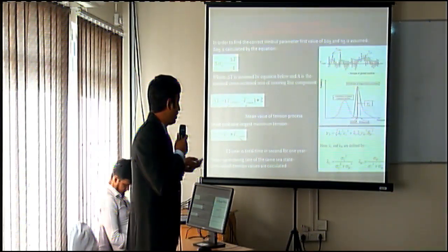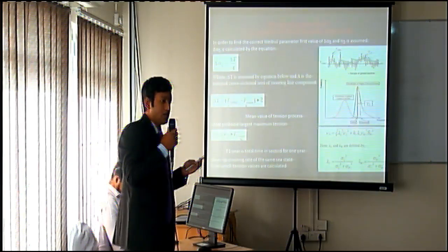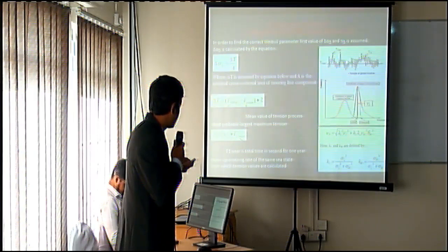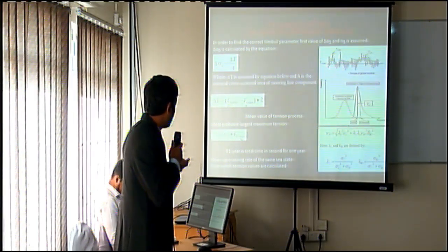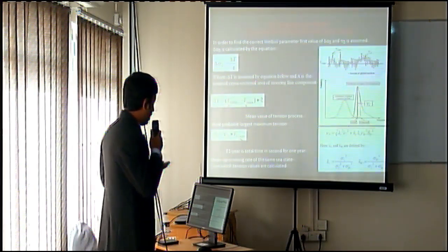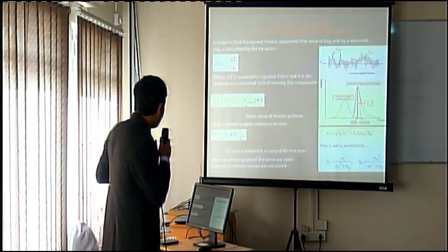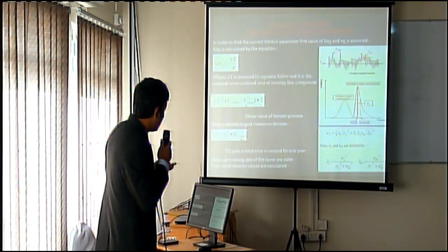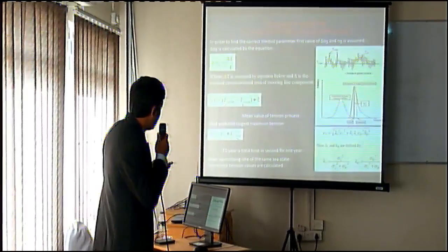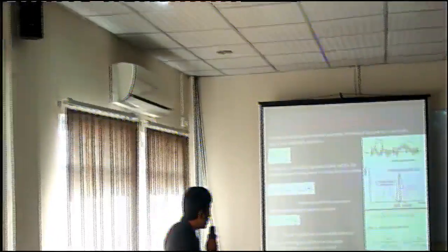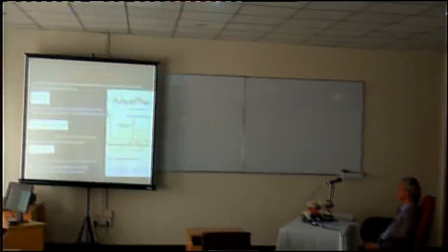And we know that the wave has two parts. One is the low frequency part, which we can see here in this curve, and also a high frequency part. For our case, we will take the tension that is the most probable largest maximum, meaning that if we do some probability analysis, we will get this value, and it should already be calculated from the ULS design condition.